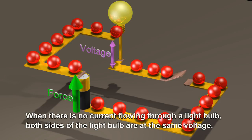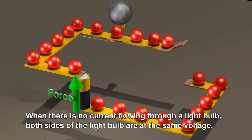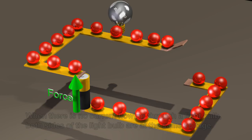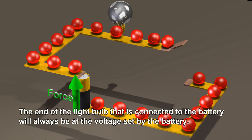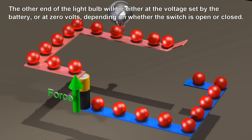When there is no current flowing through a light bulb, both sides of the light bulb are at the same voltage. The end of the light bulb that is connected to the battery will always be at the voltage set by the battery. The other end of the light bulb will be either at the voltage set by the battery or at 0 volts, depending on whether the switch is open or closed.